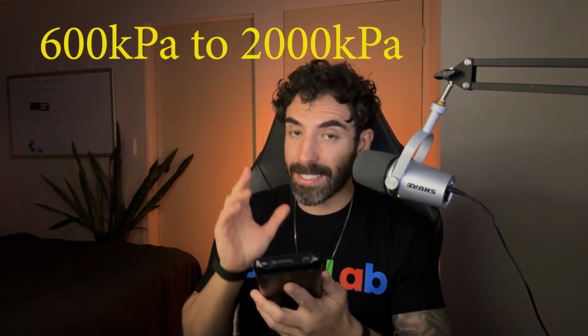If you do the maths again, for 2000 kPa times the area of that 900 millimeter diameter bored pier works out to be 1272 kilonewtons. So now we have a capacity that is 4 times greater than we could achieve with the first geotechnical report. So overnight, they had shorter piles and they didn't have to drill into rock.